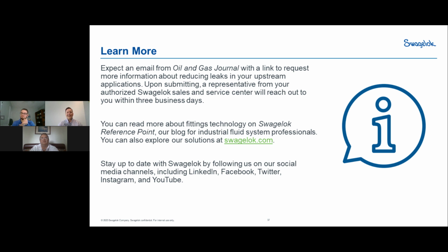Whereas something like an NPT, while it does advance down the tapered threads, it's not designed with a particular position in mind of being fully made up. So it's very difficult to create a gaugeable tapered thread. Matt, anything else from the design perspective that you'd like to add? No, that was pretty good coverage. Great. Excellent.